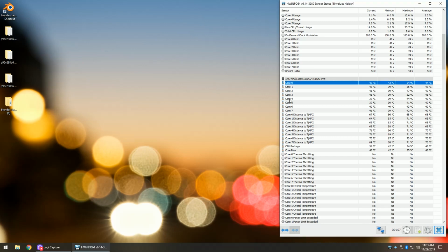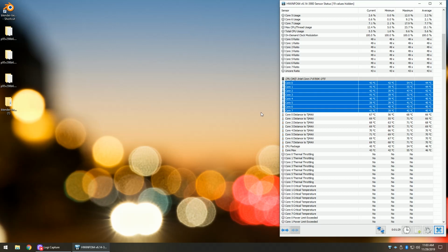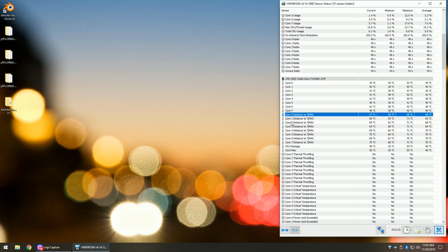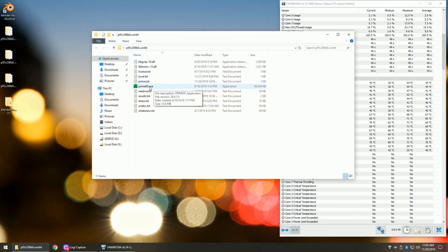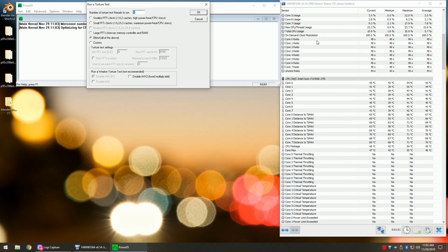Something that before I even start to go and change the settings on the hardware, I want to make sure that they're stress testing correctly, because if you're stress testing for a workload that you are not expecting to ever have your computer run, you're perhaps downclocking or overvolting for no reason. So I'm going to go ahead and just show you one of those scenarios real quick here, and we have already touched base on this, but I'm going to go ahead and boot up Prime 95. I'm going to have it run on all the cores this time on small FFTs, and I'm going to leave it set to AVX2, so it's going to generate as much heat as possible.